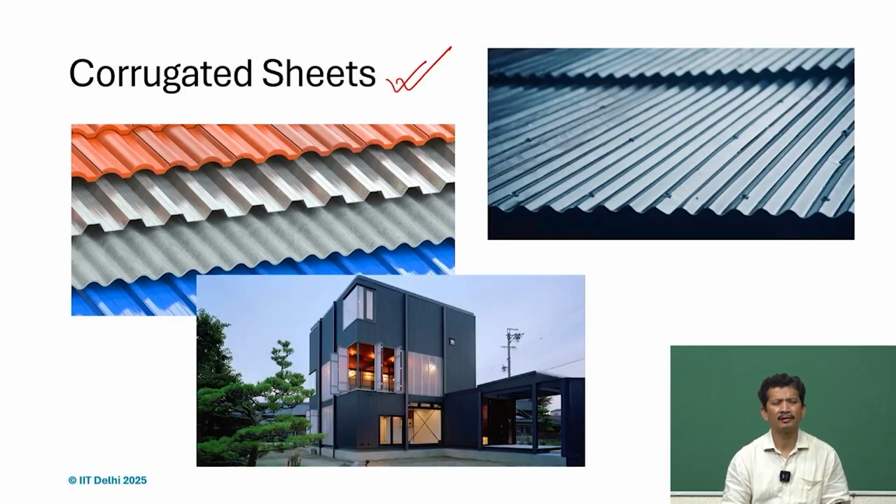And these days these corrugated sheets are used very widely because we now have many designs, many alternatives. Aesthetically also they are very good. So, we can make even warehouses, and some architectural firms even design homes using these corrugated sheets. They are very much there, and the only reason we find this wide application is the strength, and that we get mainly because of the corrugation.